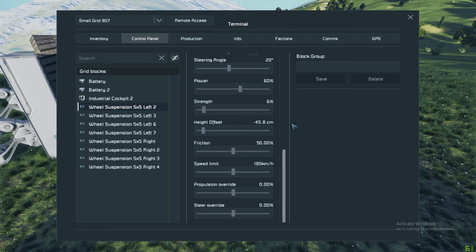nowhere. The other side of that is it might gain too much traction and you just fly off in an uncontrolled manner. Okay, so you will need to focus on the power. 60% is good. It's a good starting place. I would advise experimenting with this, depending on your rover's design and what its function is. It does go hand in hand with friction.